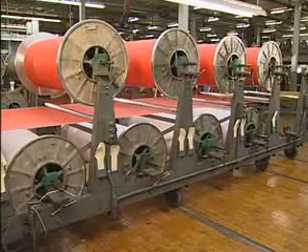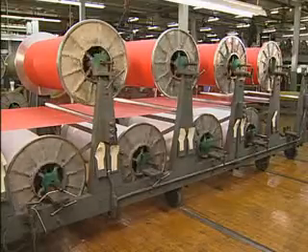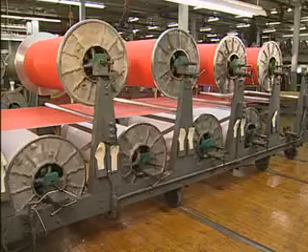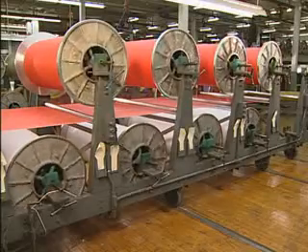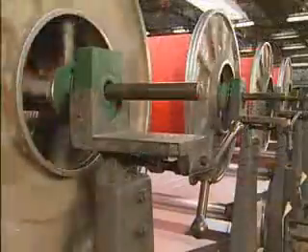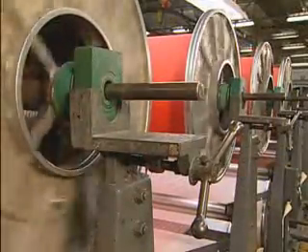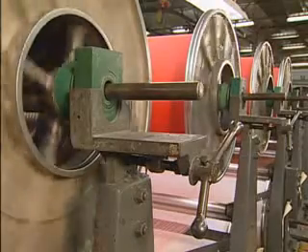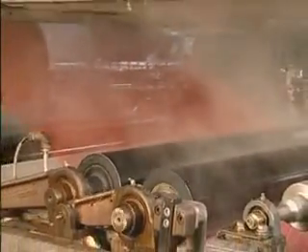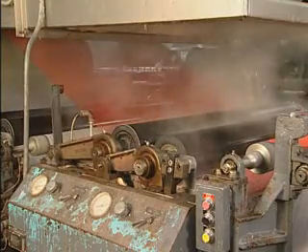The section or dye beams are placed into a slasher creel or slasher magazine, where the ends from each beam are added together so they can be sized and wound onto a single loom beam. Once assembled on a loom beam, some yarns such as plied and filament can weave without additional processing. But most yarns require a sizing with chemistry to improve the weaving performance of the yarn. This process is called slashing.